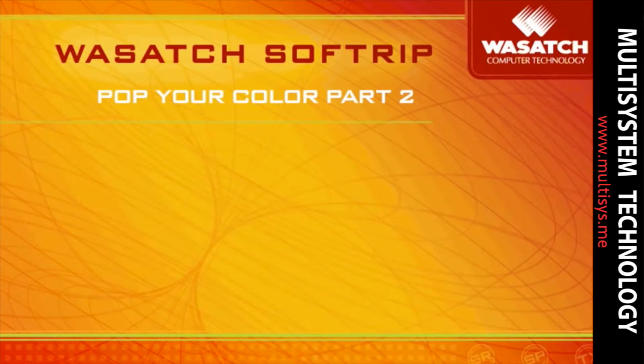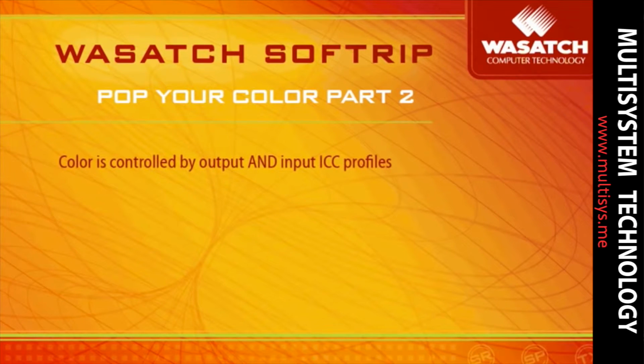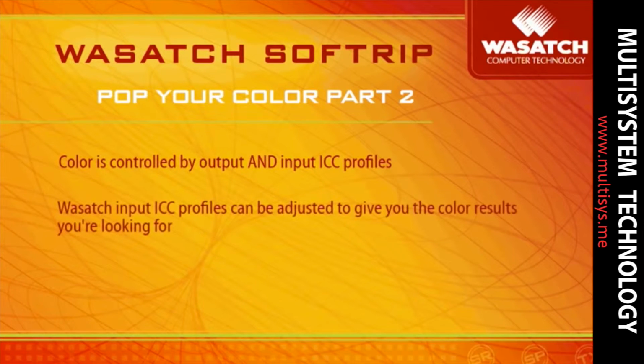In the last training video, we covered how to make your colors pop off the page. In this video, we'll show you additional ways to make your color pop using an input ICC profile. To review, color is affected by both your output ICC profile and your input ICC profile. Wasatch has a series of default input ICC profiles that it uses for images brought into SoftRIP. These defaults are industry standard, but may not provide the pop you need. You can change these to match the color settings you're looking for.